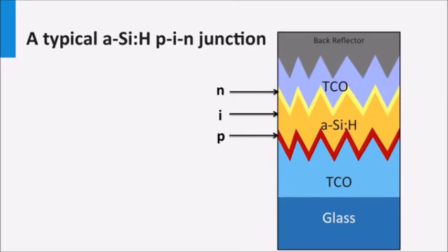Typical TCO layers are fluorine-doped tin oxide, aluminum-doped zinc oxide, boron-doped zinc oxide, hydrogen-doped indium oxide, and ITO, which is tin-doped indium oxide. These films are processed using either sputtering, low-pressure chemical vapor deposition, metal organic chemical vapor deposition, and atmospheric pressure chemical vapor deposition.